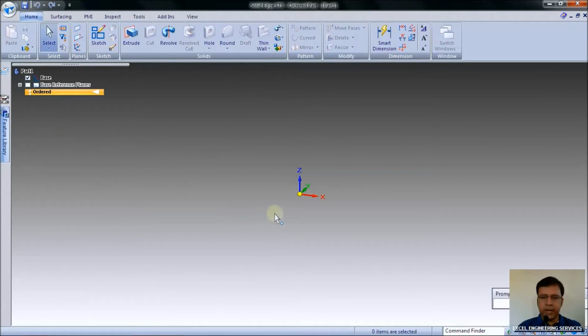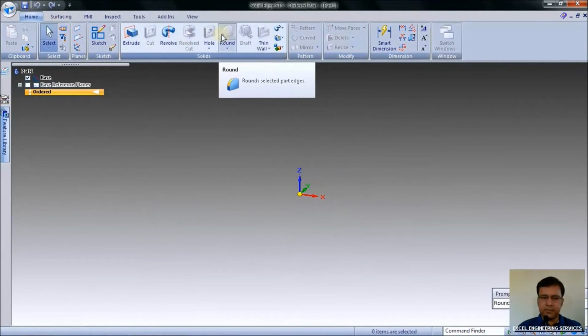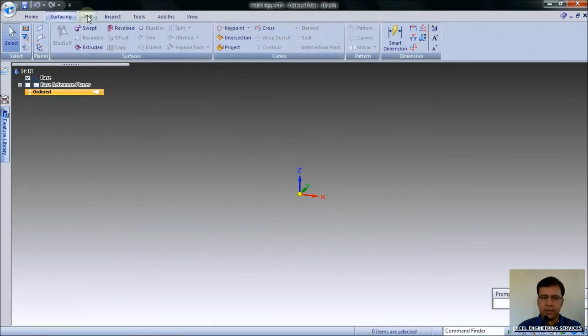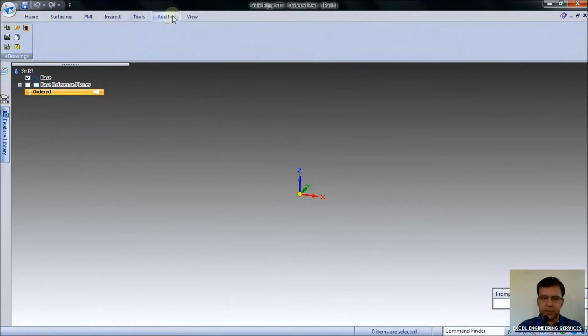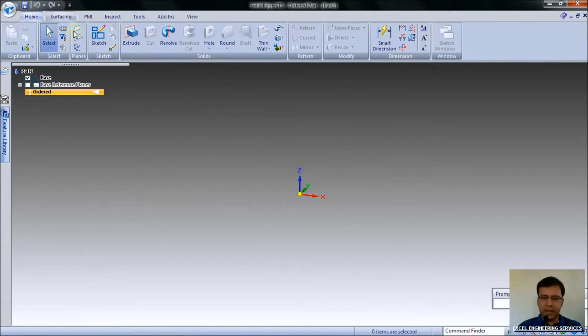and you will be greeted by a window which has a coordinate system, commands which take care of the 3D, and other tabs which we will discuss as and when encountered. The first thing you need to do is make sure the base planes are visible. Base planes are like a piece of paper on which you will be creating your sketches. Without paper you cannot sketch.